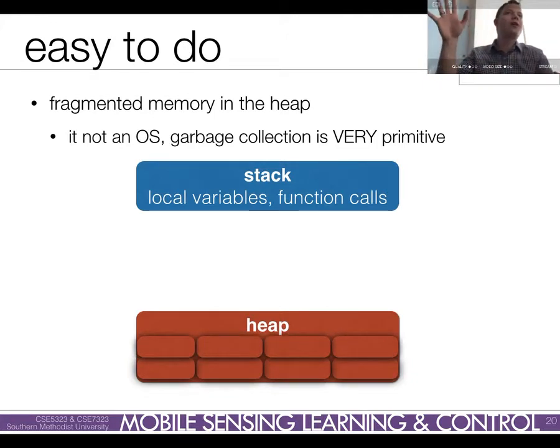Right? And then all of a sudden you look back at this and you're like, okay, I'm going to get rid of some of this that I pointed to. That right there. I'm going to get rid of that memory. I'm going to deallocate it from the heap. That's great. That's perfect. That is good programming practice. The problem is that the Arduino, when it's looking back at this, it has no idea really that that's been deallocated. The only thing that it knows is that there's other memory that's still allocated in front of that memory, physically, on the chip.